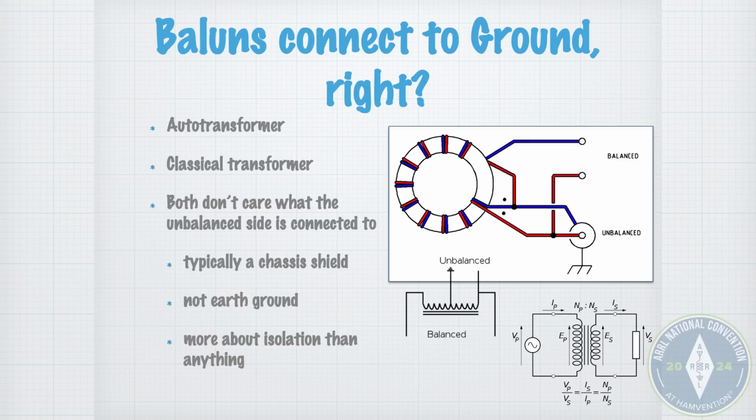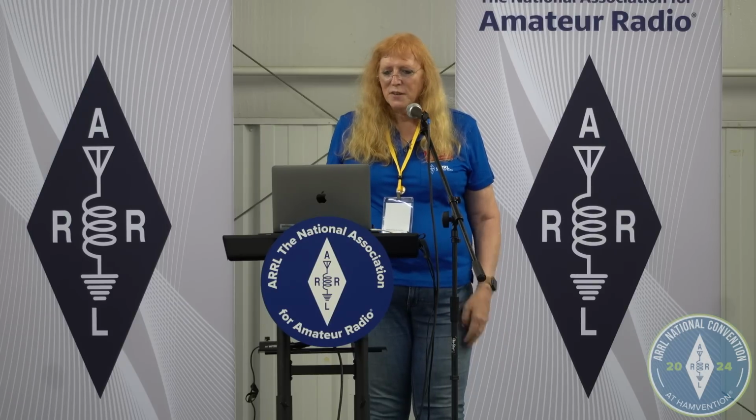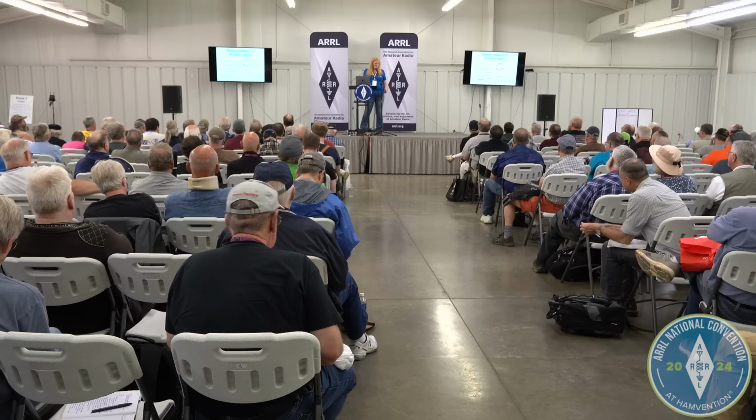So if you have a voltage coming out of your transmitter in your radio, and the chassis is one side of that, and there's current flowing out and going back through the chassis connection, which is often the coax shield, you can put that in the primary of a transformer, and then you can decouple it voltage-wise from the transmitter, and then have, say, some ladder line that will be fed symmetrically without being referenced to the voltage in the transmitter. So that's the idea there. There's no real earth ground necessary. It's just a transformer used to change voltage references around and isolate things from one another.